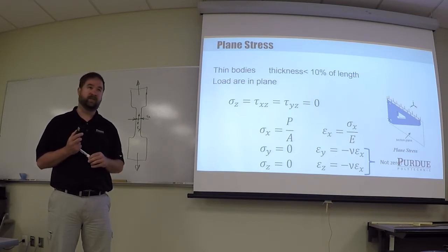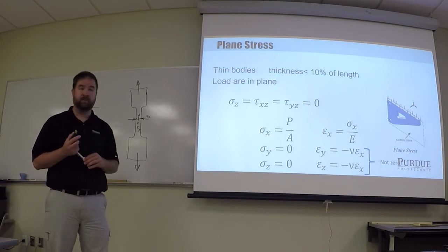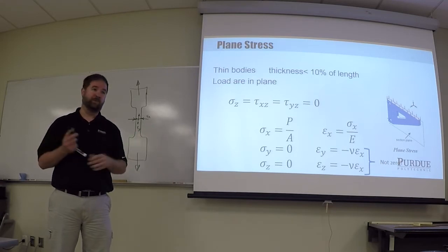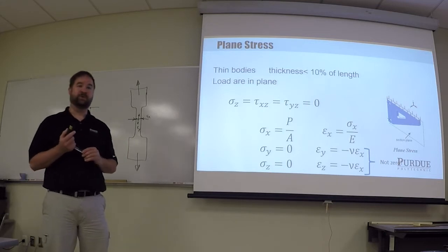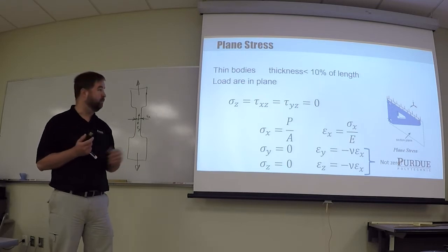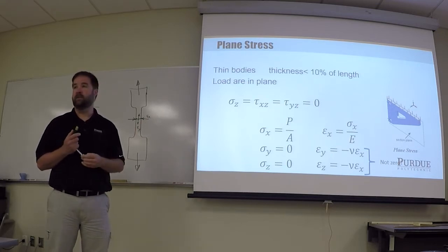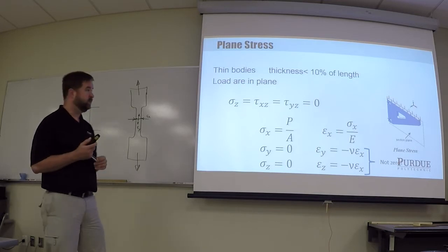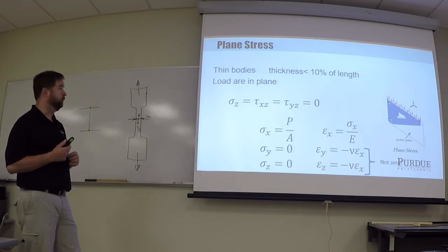Okay? Places that you can't use it would be places where the thickness is going to be important or the thickness is going to be variable. A baseball bat. I guess I'd have to qualify that further as what kind of baseball bat. Okay, a wooden baseball bat, you would not model it with plane stress elements. An aluminum one, yeah, you might be able to do it with plane stress because it's a hollow object, right? Okay? Everybody understand the kind of situation I'm talking about?